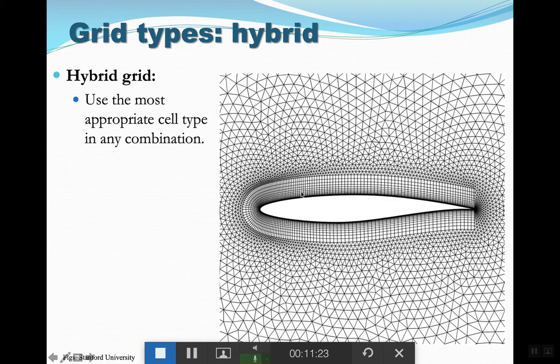For that reason, we put structured grid near the airfoil, because as you can imagine, as we get closer to the airfoil, it becomes more critical to have more accurate results. And you see this black thick line in here. Actually, if we zoom in, you will see, if I'm correct, 50 or 60 different layers of cells in here. So it's a very refined, correct mesh.